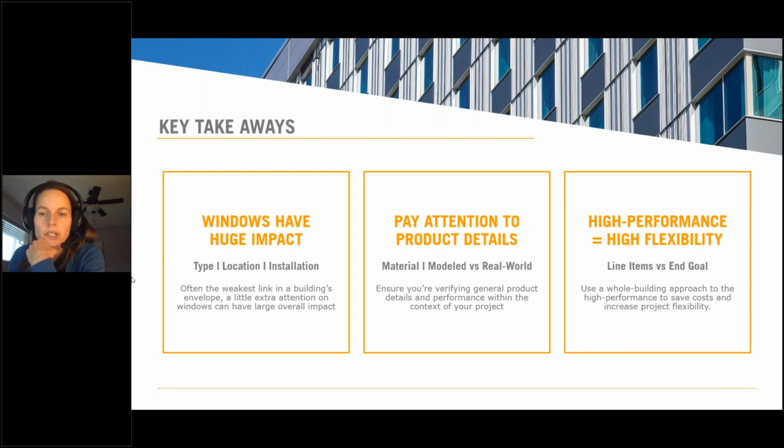Are there any window shading devices available to integrate with your system? So no, the answer to that is no, and there's a good reason for that. Windows are designed to be windows and open and just be as thermally efficient as possible, whereas shading devices put a totally different kind of load on the frame. It's structural. So we would, in any case, recommend a shading device be attached to the structure around the window.